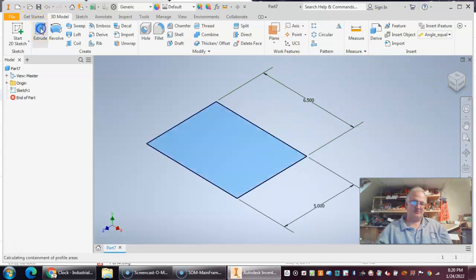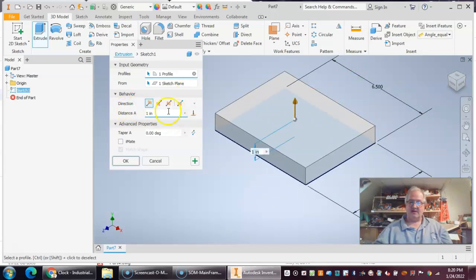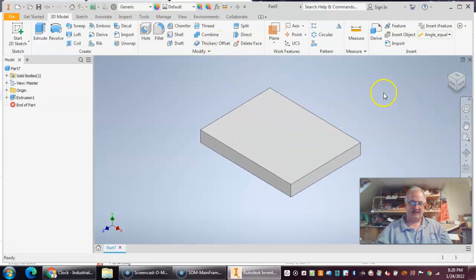And now I want to extrude this up. So 3/4. Now again, you can enter the decimal equivalent. So you can either enter 0.75, which is the decimal equivalent of 3/4, or I can actually type in 3/4. In this case, I will go 3 divided by 4, which is 3/4, and hit enter. So now I've got my three-dimensional block here.